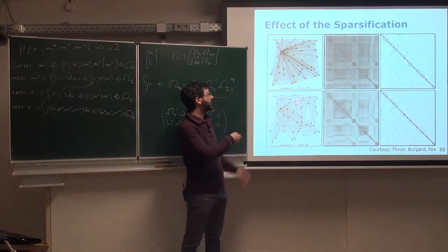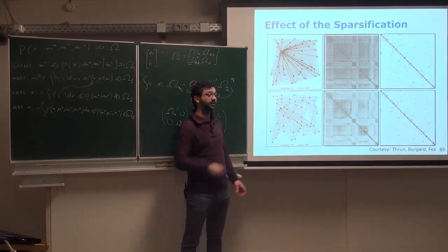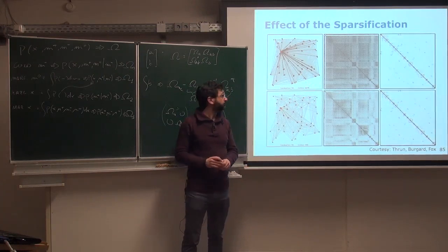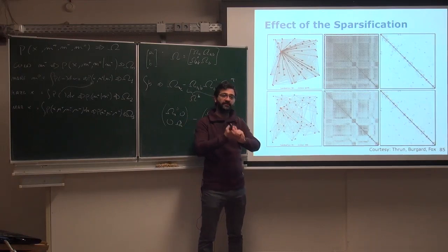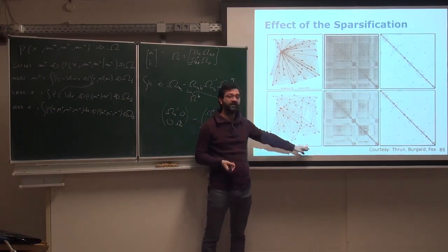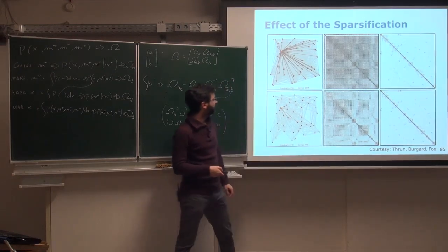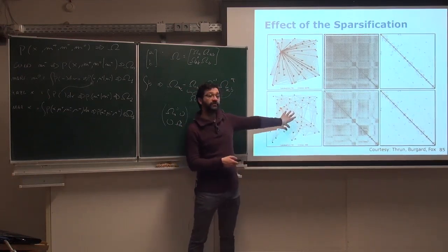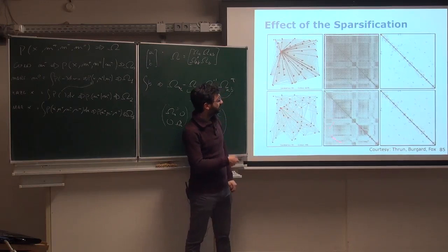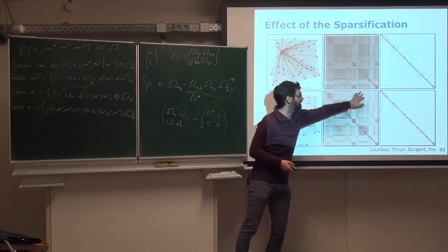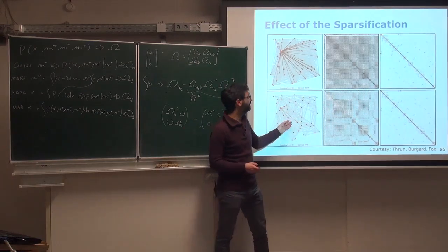So we go from 1,300 circa measurements, so like joint dependencies between variables, to something about 500. And you can see that the graph is way sparser, so there are way fewer dependencies between the landmarks in here. The covariance matrix has some weaker correlations in these parts. These are the parts where we actually cut some of the links in here.